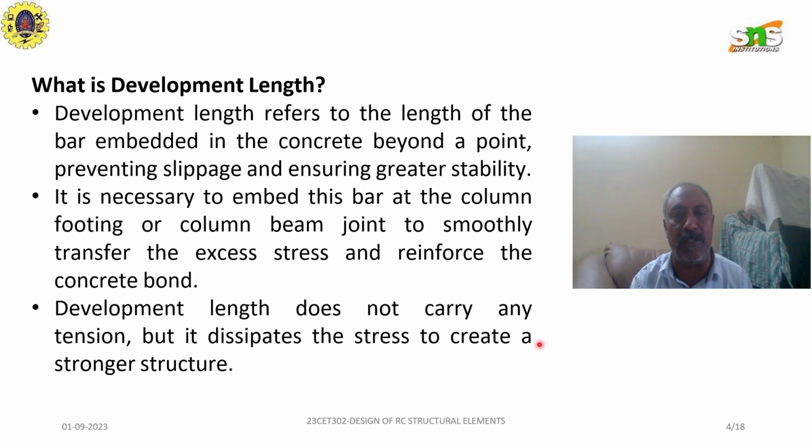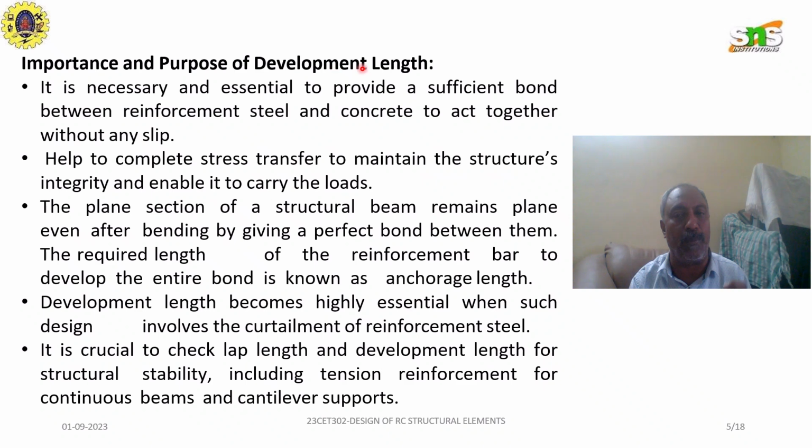That is the development length. The important purpose of development length is that it is necessary and essential to provide sufficient length between the reinforcement and the concrete to act together. It means both act together for any stresses. It helps to transfer the stresses, maintain structural integrity, and enables the member to carry all the loads.